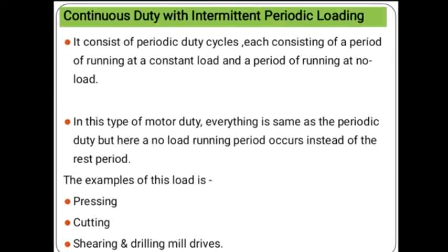Now next one is continuous duty with intermittent periodic loading. This is the same as the intermittent periodic duty with starting. How it is the same, we can see. It consists of periodic duty cycles, each consisting of a period of running at a constant load and a period of running at no load.